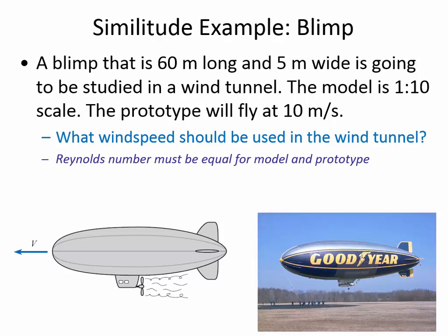It's about the forces, right. And a thing that's small resists forces more easily than a thing that's large. And so we need the wind to be moving very fast over that small object so that there's a dynamic similitude. So this method will never guide you in the wrong way. You can always use this dynamic similitude method for the types of problems you're going to see that are asking you for a size scaling difference.